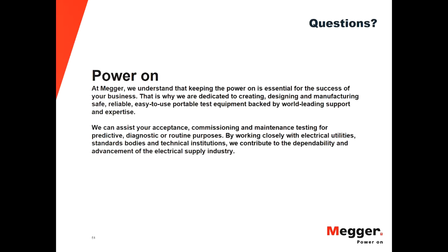If the battery is operated at elevated temperatures and the life of the battery has to be reduced, is the expected service life also reduced? Should the annual performance test be done when this new expected service life is reached? The service life that's provided by the manufacturer is provided on the basis that the batteries will be operated at 25 Celsius or at a standard temperature. Temperature plays a major role in the life of the battery. If the batteries are stored at a low temperature, then that slows down the chemical process in the battery. If they're operated at a high temperature, then that causes deterioration in the battery, and the service life is reduced, as you said.